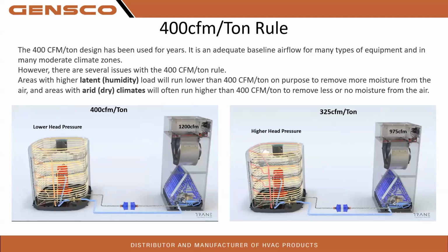The nominal or what's listed for tonnage on that piece of equipment often is not what the equipment produces at a current load condition. So just because it's a 2-ton system that's designed for, let's say, 95-degree outdoor, 80-degree indoor return air temperature, it can easily produce under 20,000 BTUs at 73-degree indoor and 97-degree outdoor temperatures. And your CFM per ton will actually be much different than intended.